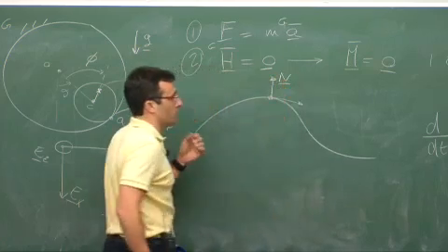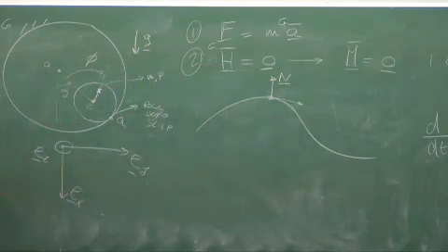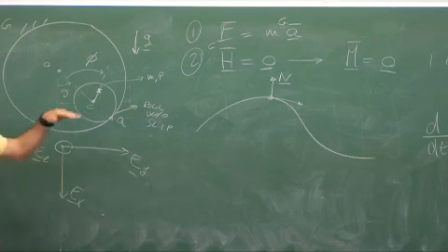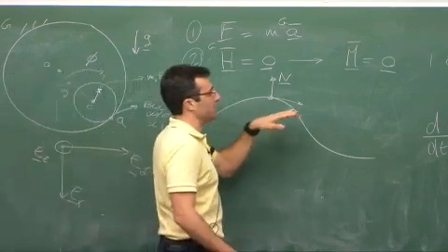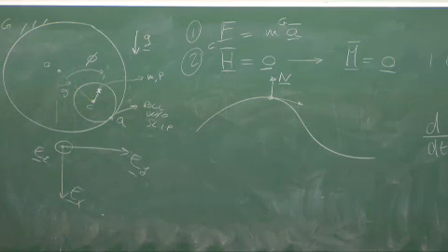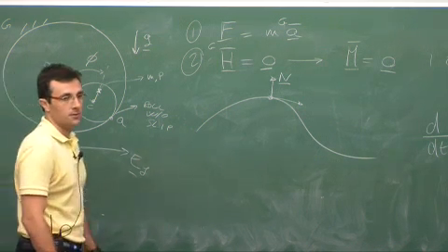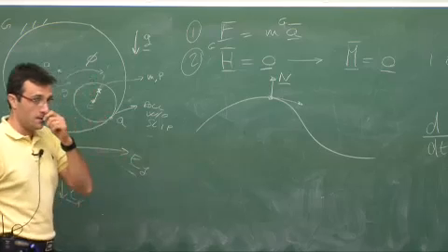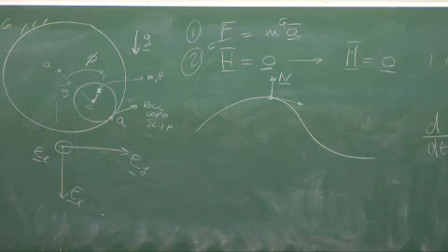And we said in general, it's a normal force that keeps me there. And you may have friction, but when you freeze it, you don't care about the friction, right? Because it's frozen. There is no actual motion. There is no elapsing of time. There is no relative velocity, so the dynamic friction is not there. What about the static friction? This is static friction. Is that a constraint force? It is a constraint force.